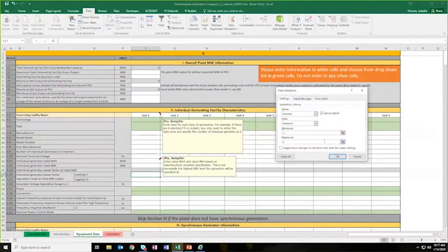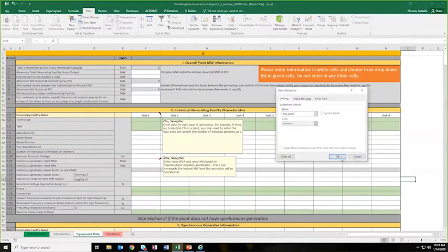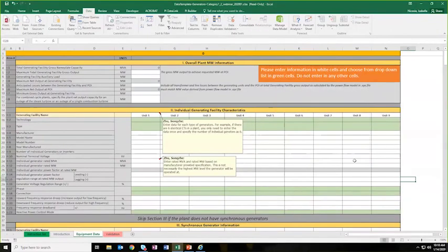You can either clear the data validation or another way is, this spreadsheet is not locked. You can make all the modifications. Those cells with validation, you can go to the data validation and remove the validation rule. Or another thing, should I tell you this trick? If you do copy paste, all the validation is bypassed. So if you enter -1 somewhere else, then copy paste into that cell, it will be accepted.